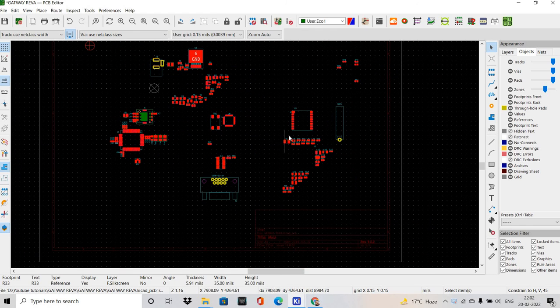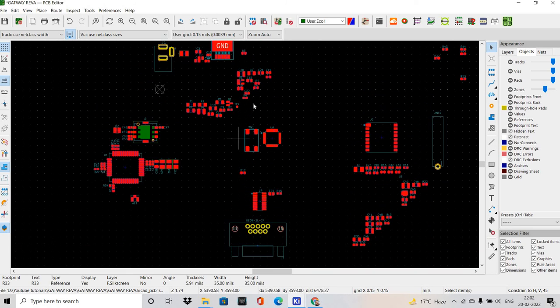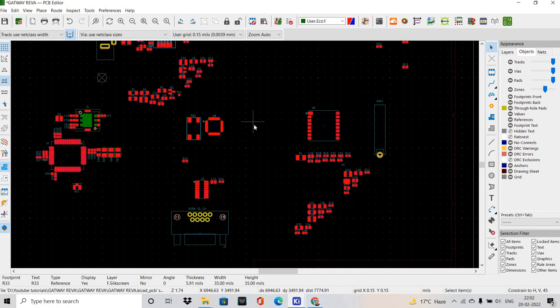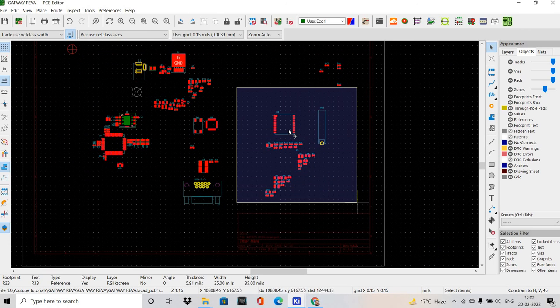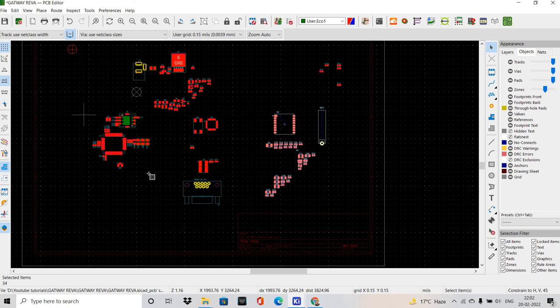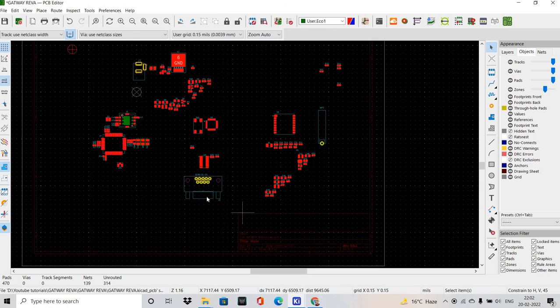As per our block diagram, we have our GSM, LoRa, power section, debug connector, and the controller, right? I was planning to do the layout in this way, keeping the LoRa module at right, GSM on the left, MCU in the middle, and DB9 just right here for the debug. I'm going to keep this power connection at the upper side. Then I will define both sides of it.